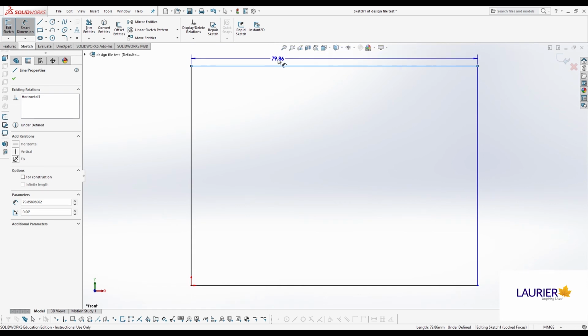So about 1 height of the font is a good distance, and we want it to be in the middle, because if it's in the middle of the line that we're measuring, it's quite intuitively obvious what line that dimension applies to. But if we had a drawing where we had several dimensions on the same vector, say 3 horizontal dimensions, and we stacked up the numbers on top of each other like the actual fonts, it's going to be difficult at a glance to know which number applies to which of those horizontal dimensions.